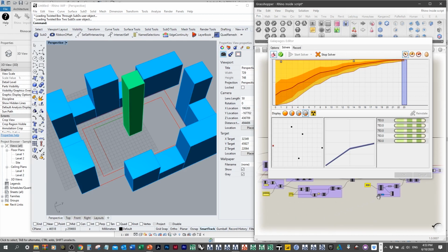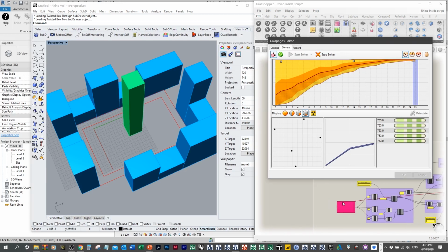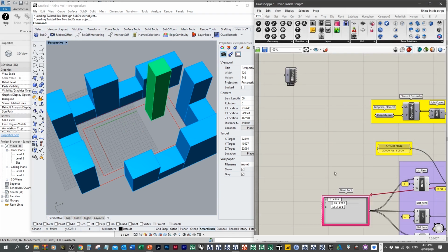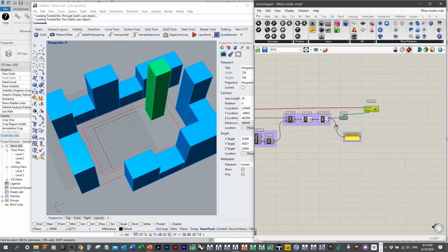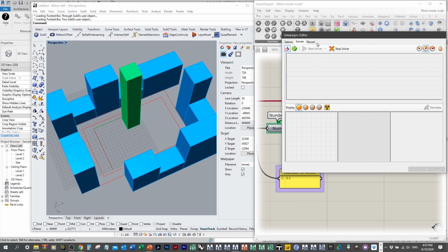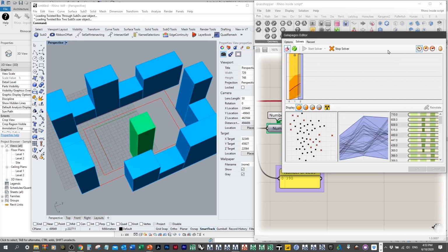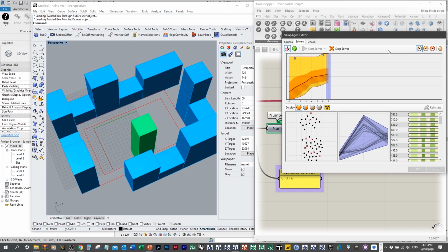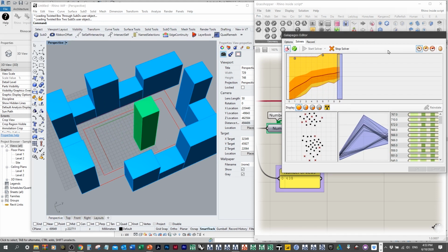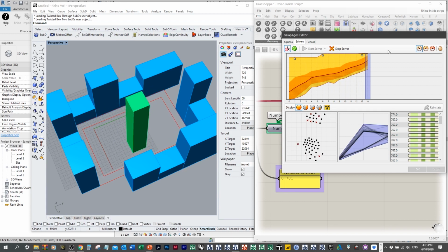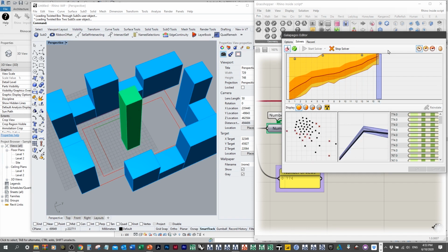And in this case, I could typically just go back, stop the solver, shuffle my gene pool, and just start again, just to make sure that we're not making too much of an assumption. But there is some degree of sort of human interpretation of what's being shown to us. So you do have to be careful with evolutionary solvers that there might be multiple optimal outcomes for your study, and you might just be happening to miss one of them. We can see again, we're getting a pretty similar result, but I find sometimes with this particular study, actually no good, it did find a different result.